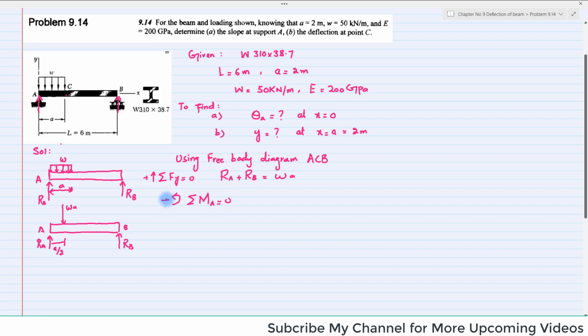taking counterclockwise as positive. You can see one moment is wa into perpendicular distance a by 2, and it is clockwise, so it will be negative. Clear? And the second moment is RB into perpendicular distance, which is total L, so it will be plus RB into L. Their sum must be equal to 0. When you solve this, you will have RB is equal to wa squared over 2,